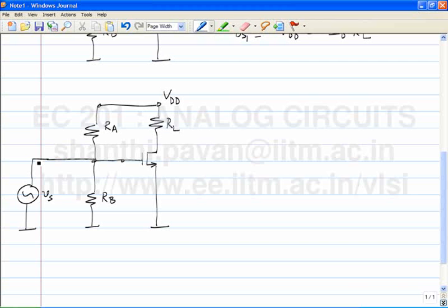And we figured out that the reason current was flowing into the small signal source Vs at the operating point was because the DC potential on either side, before we made this connection, is not the same. So an easy fix for that problem was to put a battery here having a value VGS1. If this was VGS1 and this was VGS1 before you joined them, obviously once you join them, the potential is going to remain the same. So what we did was this. And then we come back to the same old problem: the whole idea in doing all these antics was to get rid of the battery in the first place, and now we seem to have gotten back to a situation where we have a battery.